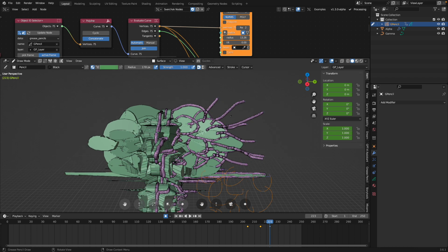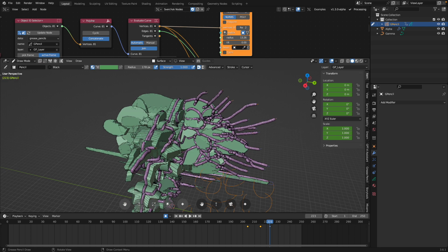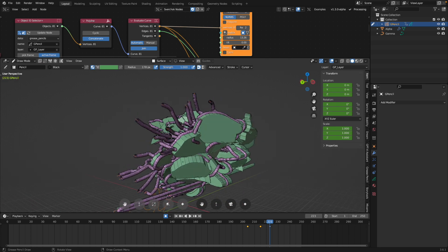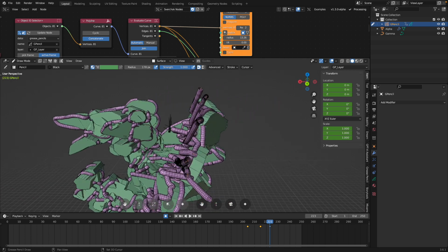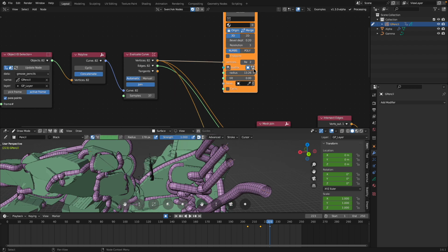This is just like the behavior of geometry nodes and curve. You can do this quite easily, but now we are doing it using just grease pencil and sphere chalk. This is, like I said, the tool that's missing from Blender Sculpt. Unfortunately, I think the side effect of this is that you need to fill the hole after, but you can do that yourself.